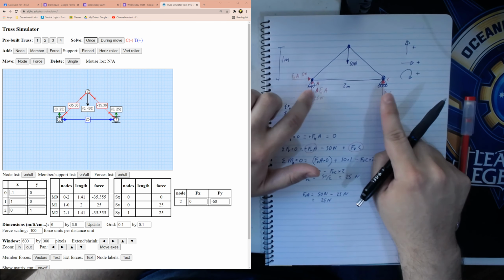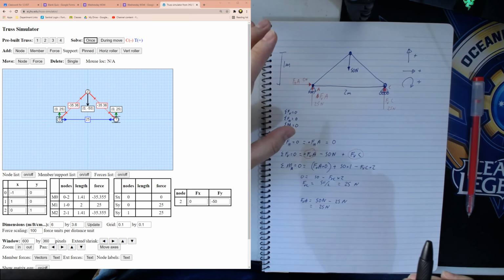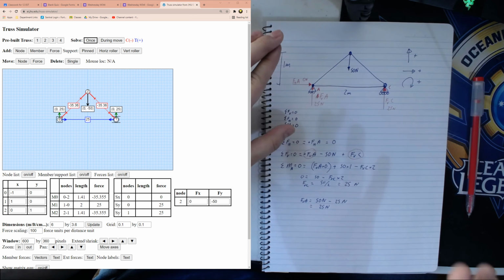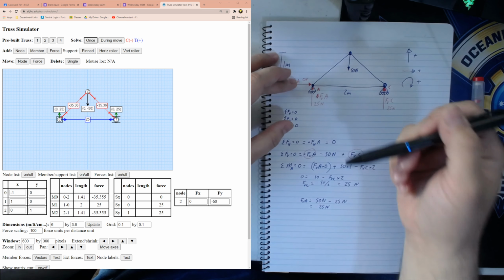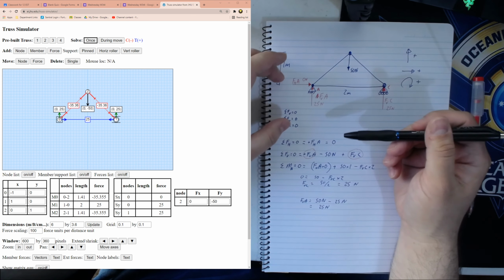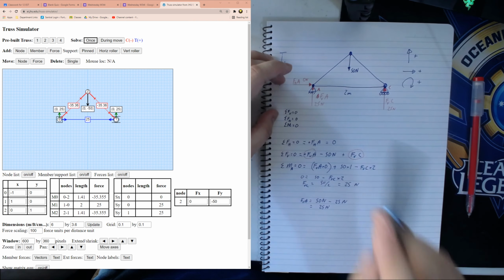We can do our truss analysis and identify which of the members is close to 100 newtons, so we can find out the force that the structure is experiencing. The reason why we're using truss analysis is that it allows us to do this next step. We can find what forces it's experiencing because we can zoom into an individual part of the bridge.